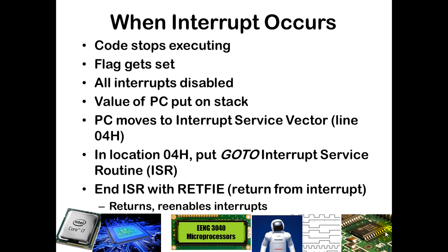And so if you have an interrupt and the timer 0 interrupt flag is set, then you know that the interrupt came because the timer 0 overflowed. If another flag was set, then you would know the corresponding interrupt was triggered. Otherwise, you don't necessarily know which interrupt was triggered unless you happen to have only enabled one. But in most sophisticated programs, you want several different interrupts to be capable.